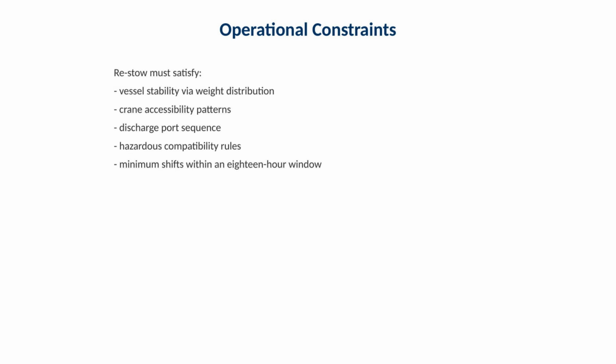The operation must satisfy vessel stability through weight distribution, and it must respect crane accessibility patterns, because not all moves are equally easy within a tight port call. It must also respect the discharge port sequence so earlier ports remain accessible, comply with hazardous compatibility rules, and minimize shifts within the 18-hour operational window.